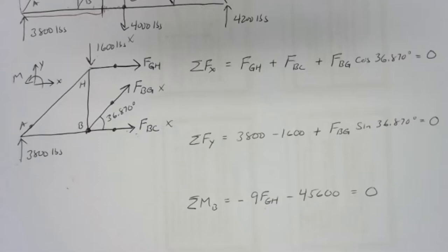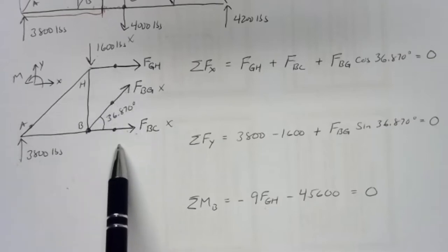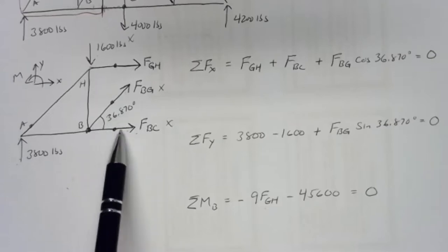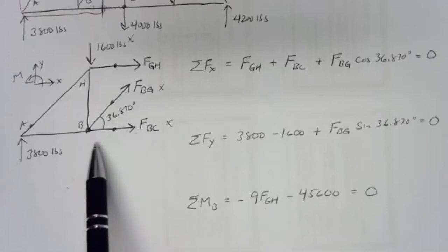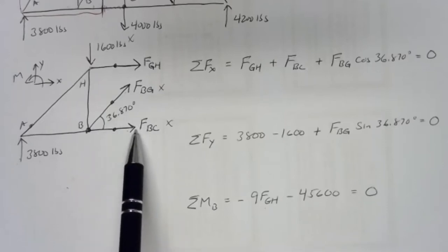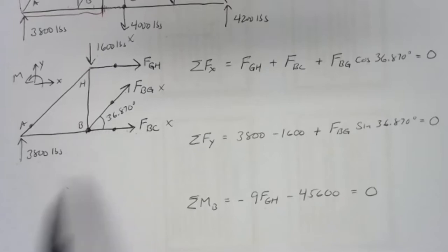So interpretation of tension and compression is much, much simpler in method of sections because we essentially build it into our assumption. We assume everything's tension. And when our answers come out positive, remember, positive answers mean our assumptions were correct. When we get a positive answer, we have tension. If we get a negative answer, that really means that the rest of the truss pushes on the member instead of pulling on it. So that puts it into compression.